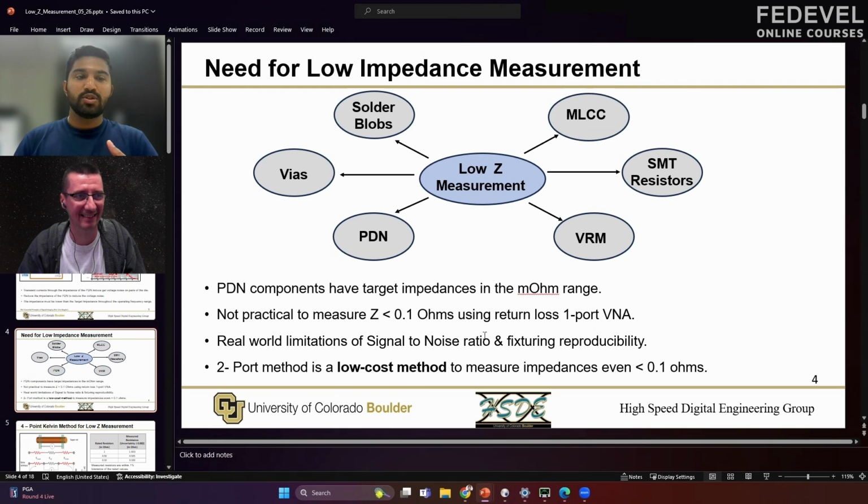So just to repeat what we just discussed, the measurement of the impedance of the entire PDN is a different study altogether. But to be able to do that, first we need to be able to measure the impedances of these individual components, and that's what we are going to look at today. And obviously with this low cost SDR VNA, and with a free tool which is Qucs. But theoretically, once we learn how to do this for, I don't know, a resistor or capacitor, you can measure it also on your own PCB, same way. Yes, definitely we can, but to be able to measure it is one thing, and to be able to analyze it is another different thing.